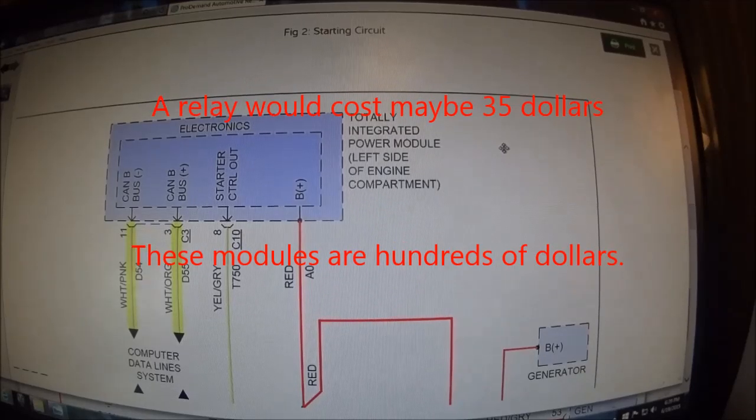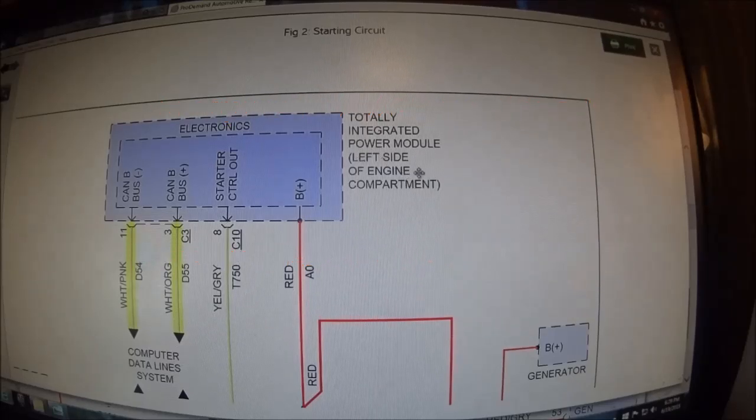Okay, so that's how we came to the determination of a broken wire first, and then a bad integrated power module. This kind of problem could be, like I said in the beginning, a nightmare to figure out. It didn't have one issue; it had two. And I don't know how either one of them occurred. Like I said, the wire was repaired once, so the repairs seem to be pretty good.